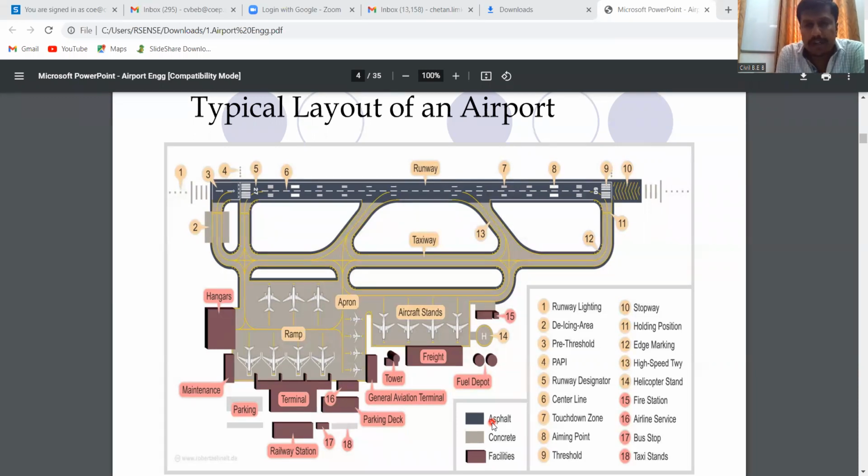If you take the rigid pavement, it's a hard material or hard surface, so more friction is there. And as there is more friction, there is more wear and tear of the tire as well as of the road surface. But in case of the flexible, friction is comparatively low with the rigid pavements. So there is less wear and tear in case of asphalt pavements, and that is why we prefer asphalt pavements for runways. If somebody asks you why the runways are always of asphalt pavements only, that is the reason, the friction we need to consider, the technical point.